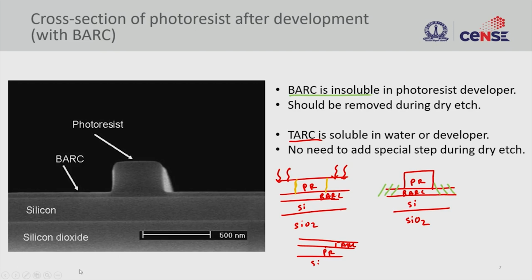So, in this case again, let us say it is positive resist, you are exposing it, your top anti-reflective coating layer should also be transparent to your illuminating wavelength, which is again a very crucial requirement. It could be anti-reflective, but at the same time it should not have large absorption, right.